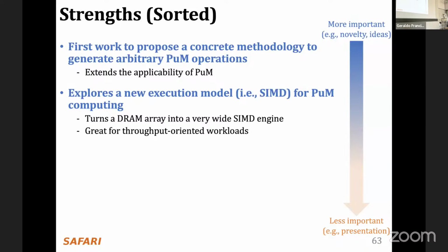The second item is that it explores a new execution model for processing-using DRAM computation. This is more related to implementation, right? By implementing that idea, I can enable something. And this enabling here is this very wide SIMD engine inside the DRAM array itself.